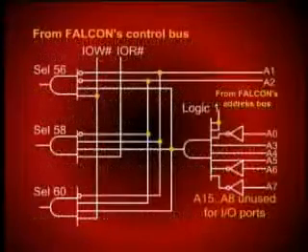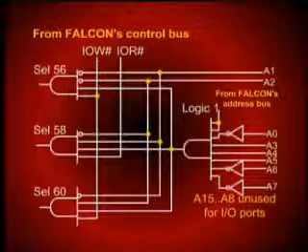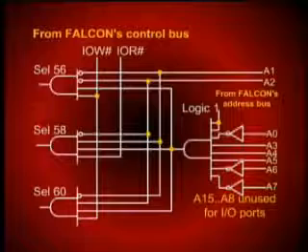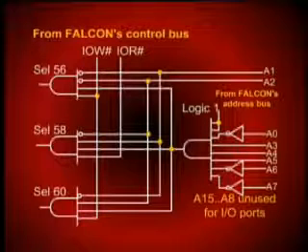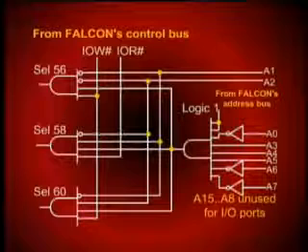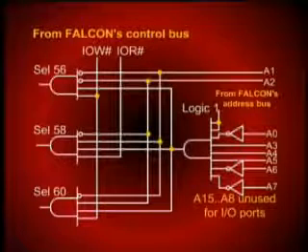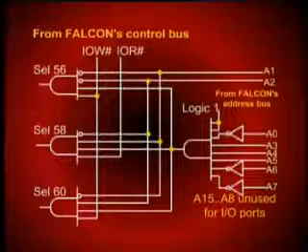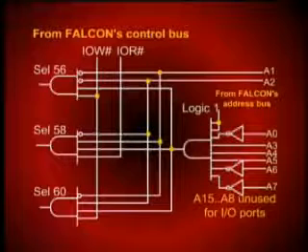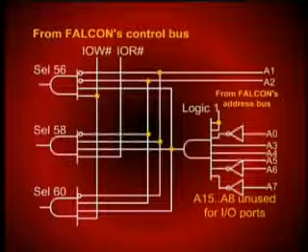The logic diagram of the address decoder is shown in the figure. Note in this figure that the 8 input AND gate uses only 6 address lines, A0, A3, A4 onwards up to A7. The 2 unused inputs are tied to logic high, logic level 1.